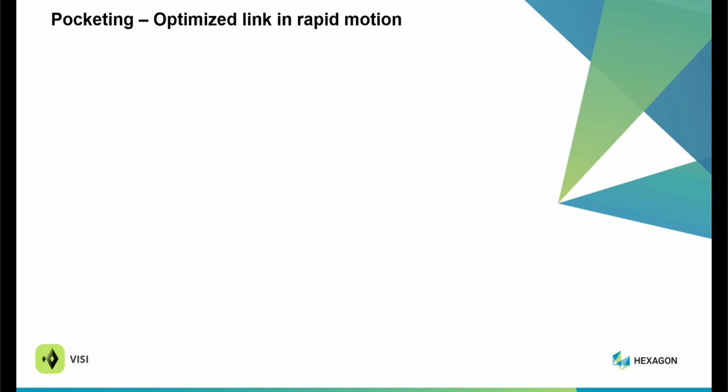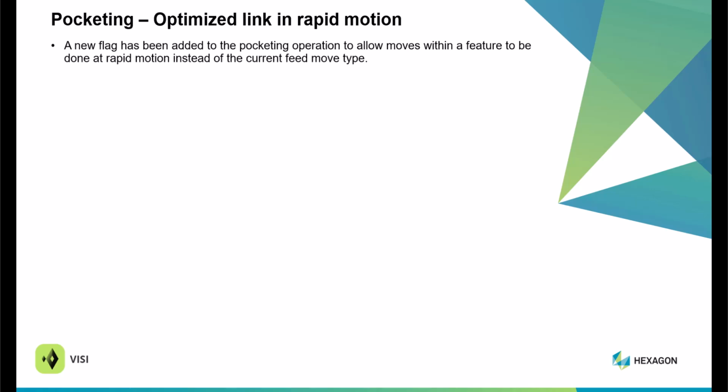Pocket optimization, linking, and rapid motion. A new flag has been added to pocketing operations to allow moves within a feature to be done on a rapid motion instead of the current feed movement.